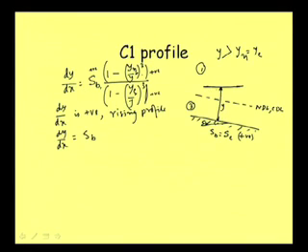So, if I draw a line parallel to the channel bed, then the slope at any point, dy dx, indicates how much slope the profile is making with respect to the channel bed, because depths are measured from the channel bed here. And that is why dy dx equal to SB means that this slope is also SB.